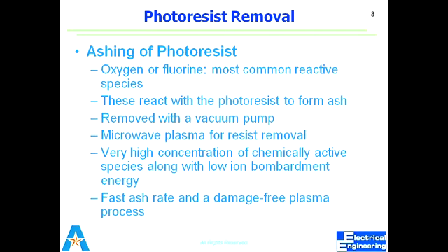Okay, so we are talking about dry etching. As I told you, oxygen or fluorine can be introduced as a reactive species when we are doing dry etching. What is the effect of oxygen and fluorine? They can increase the etching process. How they increase it is why you need to know about the H by C ratio and F by C ratio. Right now I am not going to talk about that, but you should know that adding fluorine or oxygen actually affects your etch rate in dry etching.